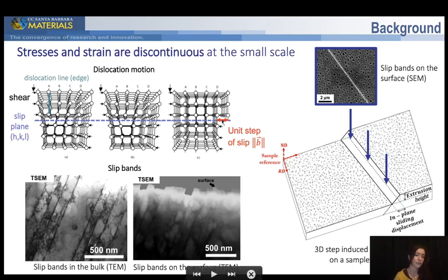These kinds of defects are called slip bands and are shown on this micrograph. When all these dislocations on the same plane emerge onto the surface, they will create substantial steps, as shown on this cross-section image.